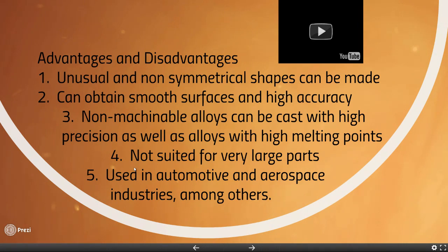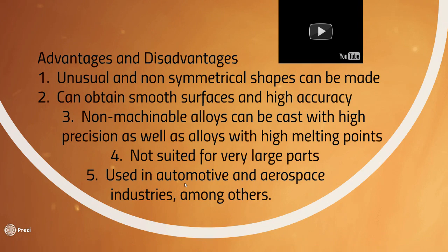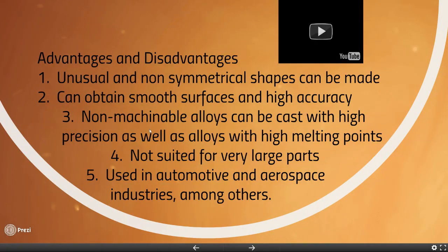Now, investment casting is not suited for very large parts, so you won't find huge parts that are investment cast, but you will find a lot of these parts used in the automotive industry, aerospace industry, any industry with high performance and that needs parts with very, very tight tolerances. And also needs parts which are very strong, which means they will be non-machinable or they'll have high melting temperatures.